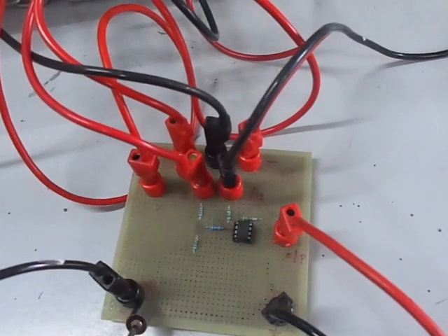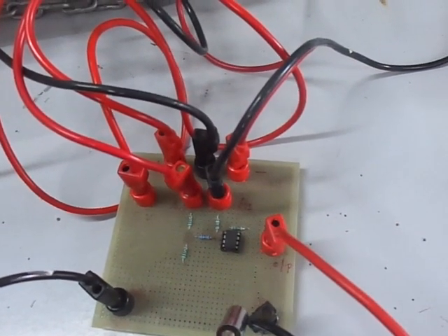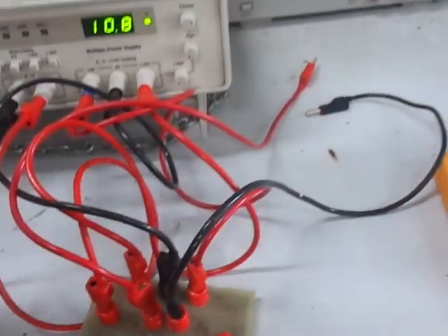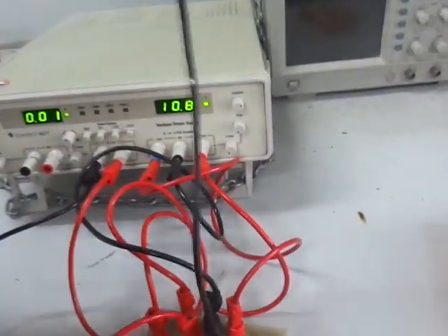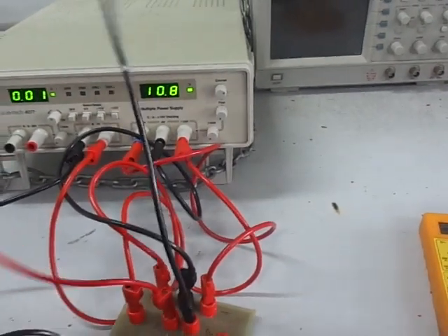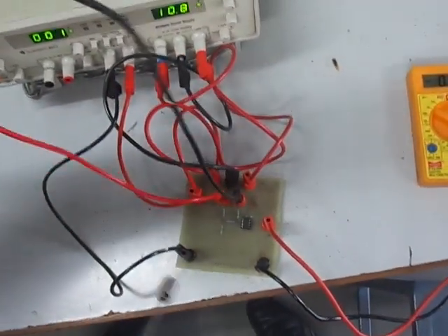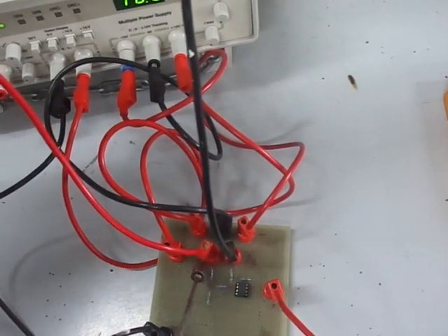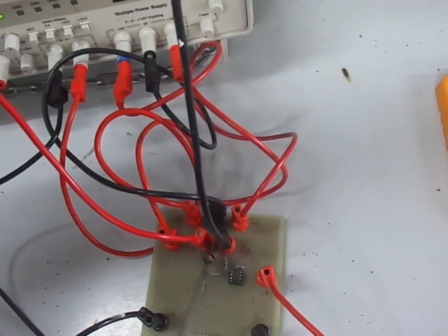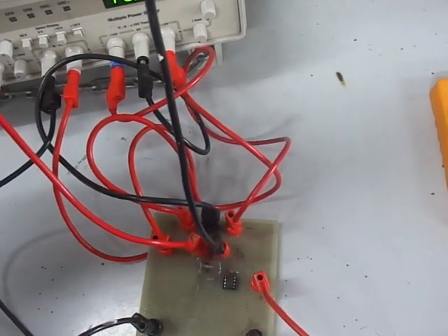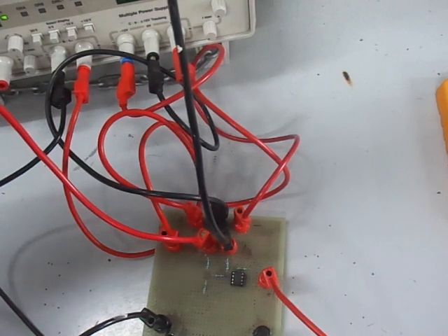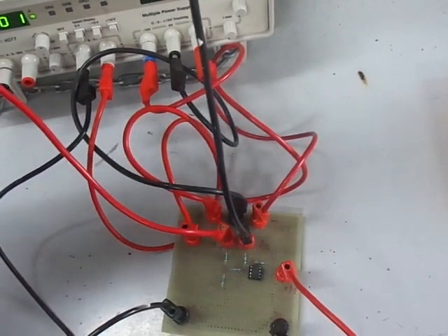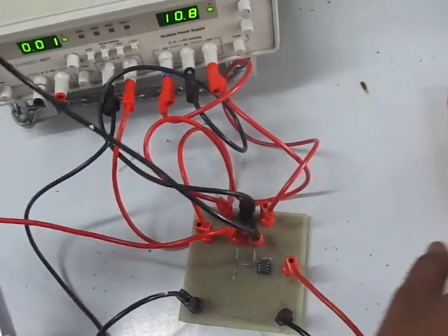Between these two terminals the 5 volt supply is connected, and between these two terminals we are going to take the output, which is measured on a multimeter. These are the two wires we are going to take. This is the A1 terminal and this is the A0 terminal. Right now these terminals are not connected anywhere. We are going to connect these terminals, means A1 and A0 we are making 0 0, connecting to ground potential, then either to the 5 volt supply or ground continuously, and then we will observe the output voltage.